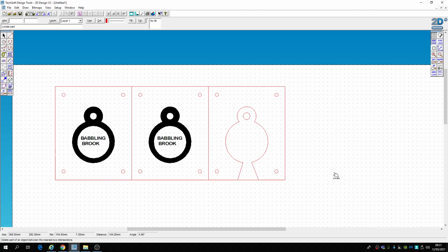So basically now you've got two outer faces and a core, and when you bolt that lot together, obviously the right way, your pewter will come in via the funnel and fill up that area, with that etched out and the writing etched out, which is what you're going to set it to do. You're going to set the black to engrave and red to cut, and you end up with a nice little mould for a medal. So there you go. That is a basic little project done and dusted.